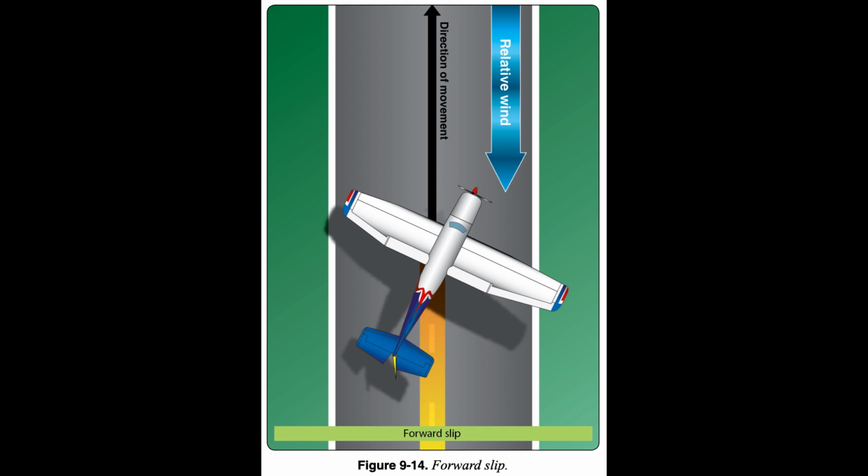When a crosswind is present, the pilot should lower the upwind wing such that the airplane is banked into the crosswind, since slipping into the wind makes it easier to remain on the original flight path. In most light airplanes, the steepness of a slip is limited by the amount of rudder travel available.